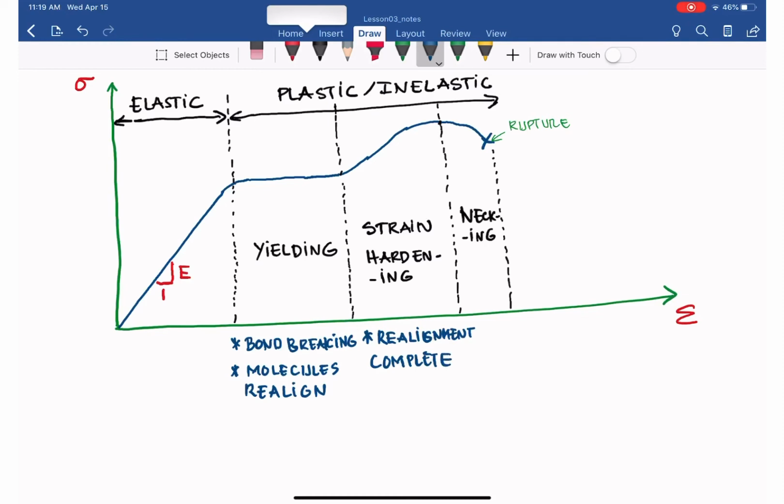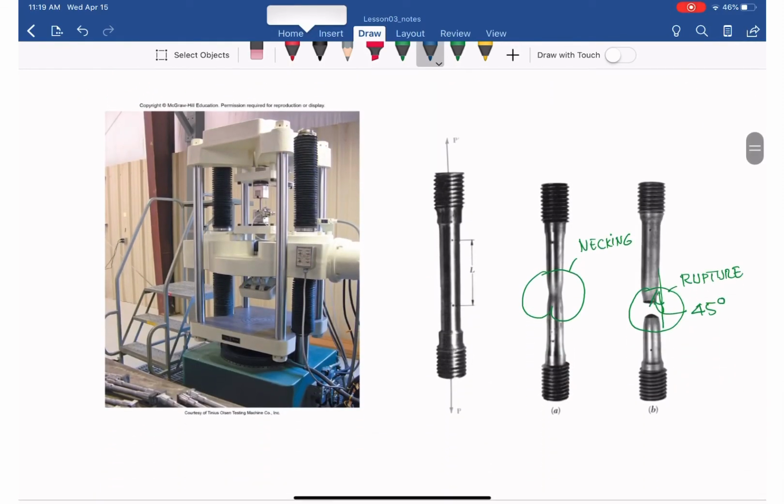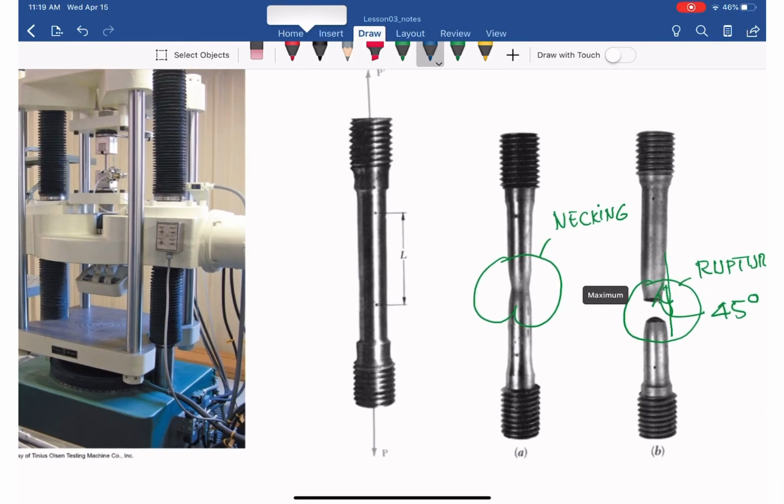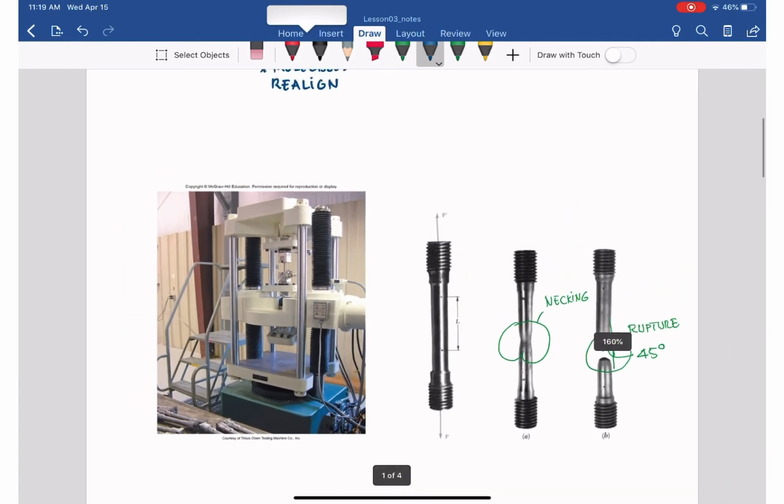And in the necking region, as you can see, the strength does not increase, while the normal stress keeps increasing, and that is called local instability in that region. Why local? We'll show you back on the figure in a second. With local instability, as you can see here, it happens at one certain point locally on the specimen, where you have necking and rupture.